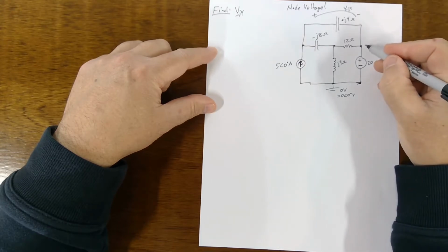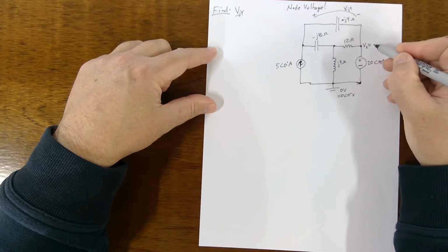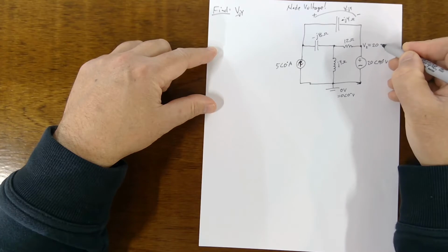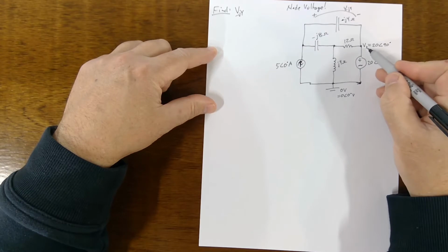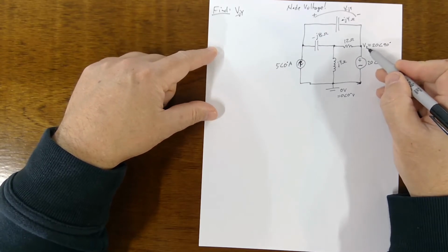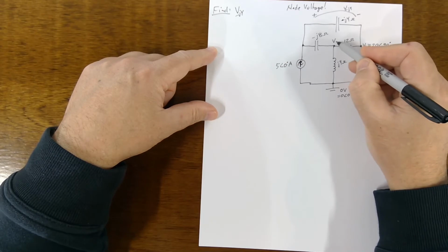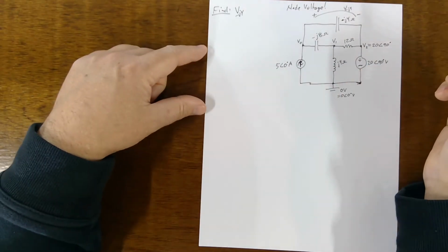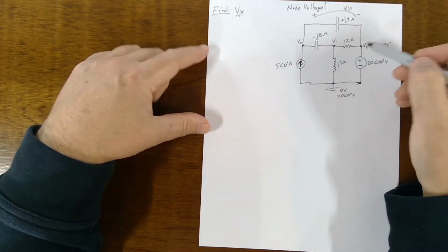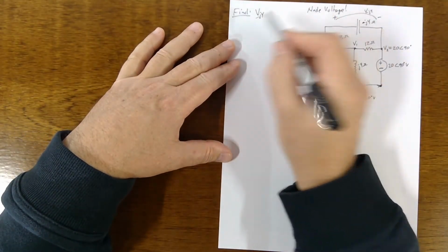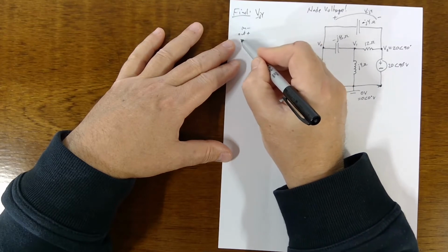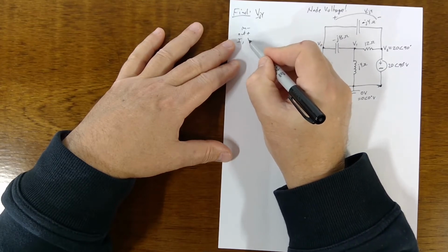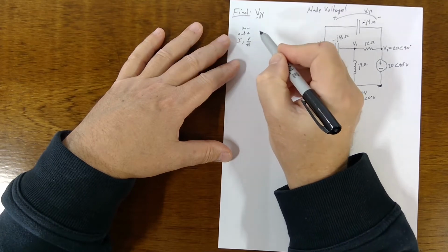Let's call it V2 for the math, but we know it's 20 angle 90 degrees at this element because it's rising from 0 to that, but it'll be convenient to call it V2 in the math, so we have to write less. Let's call this V1 and then call this V0. All right, we name our nodes. And what's the method here? In will be negative, out will be plus, and we're summing I and V over Z terms.